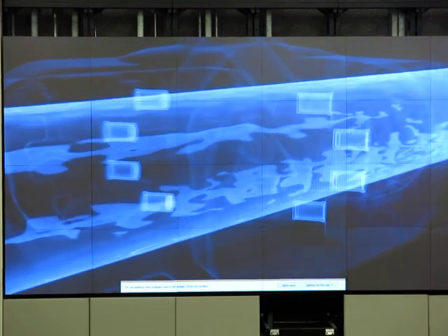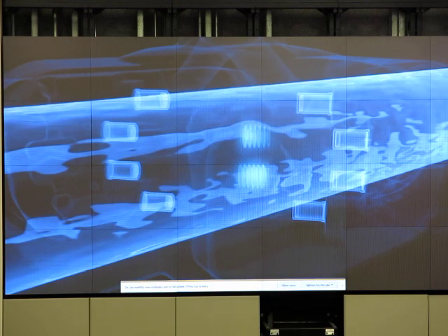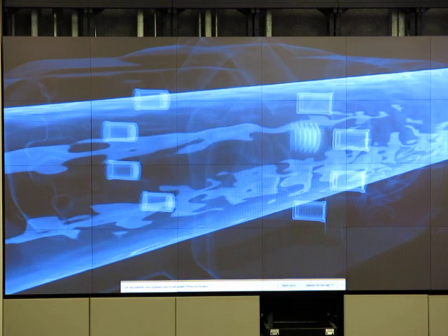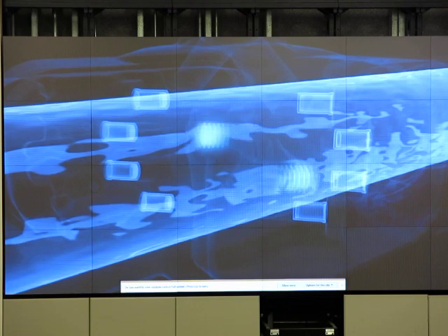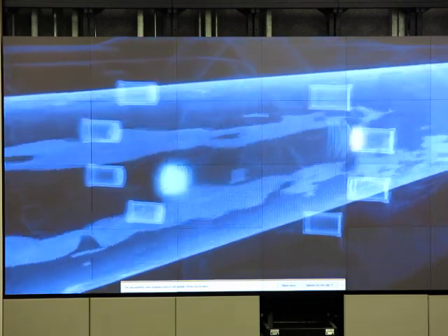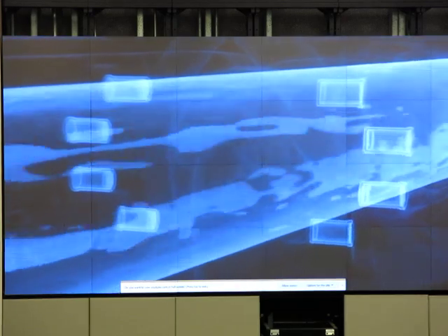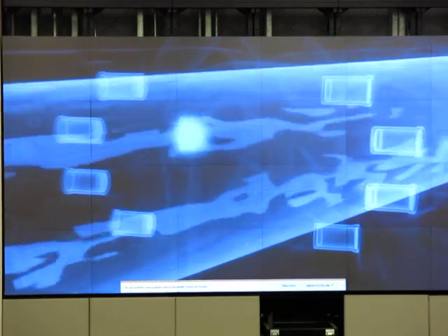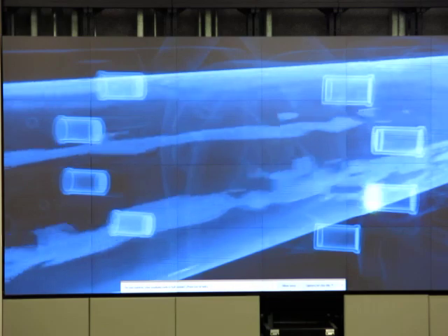By increasing the number of sensor pairs, it's possible to accurately detect and mathematically compensate for flow profile distortions over the entire pipe cross-section. When there is no flow, the signal transit times are the same, upstream and downstream. Once the fluid starts to flow in the measuring tube, the ultrasonic signals are accelerated in the direction of the flow and decelerated against the flow.